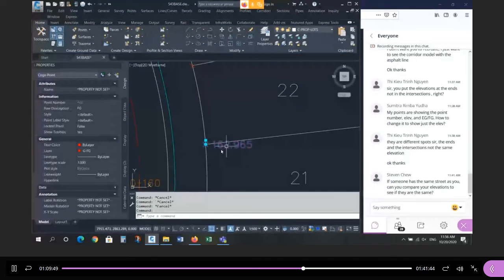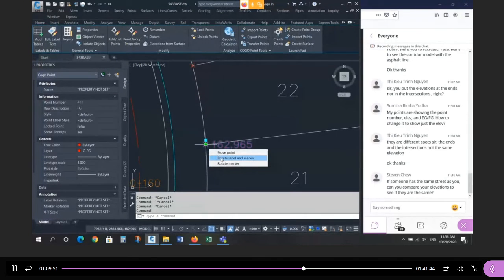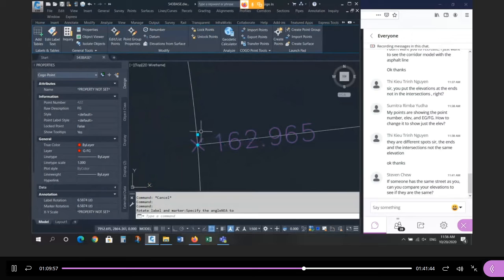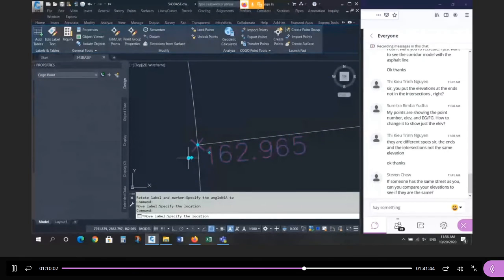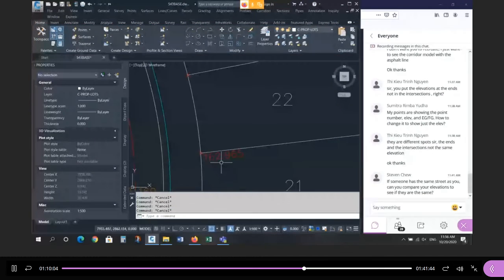Okay, let me show it again. So click here, click, go inside, choose the middle one, snap to the near point, and don't do this by eye. Make sure you snap to the line. Make sure it's exactly the same. And then now you can't read it. Put it either above or below. Make it clean. Make it look good.